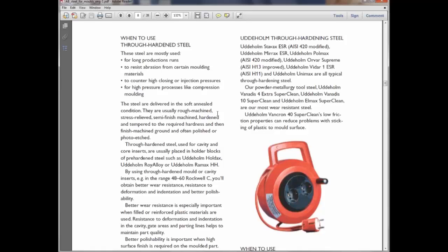These stresses are created only when we go for higher depth of cut. In semi finishing we also increase the RPM of the cutter, like we go up to 2000 RPM. So residual stresses don't get created at that time. After that, when we did semi finishing,